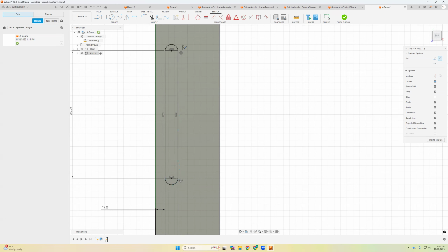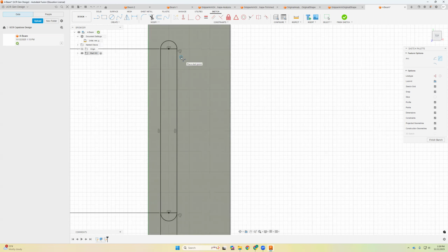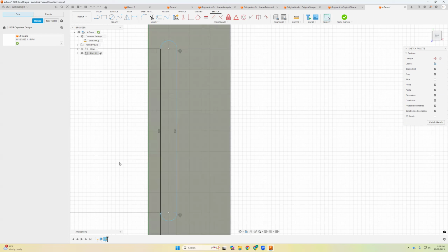And you see this tangent sign appeared here, which obviously we wanted this one to be tangent there. Now I can click that top part and delete it. Click that part and delete it. So maybe if I also click dimension and give the radius here, then later if I want to change that, I can do that as well. That's also a good idea to do.